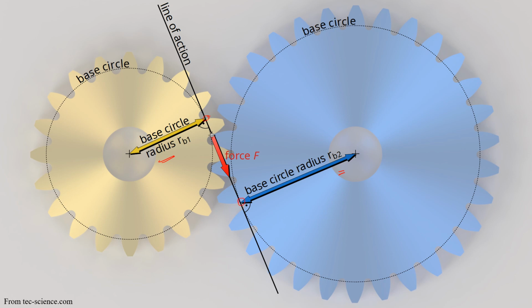This distance can change depending upon the gear ratios. The other thing you can readily realize is that the force being transmitted from the input gear to the output gear follows the same line of action. This red arrow indicates how the force is going to be transmitted from the input side to the output side.